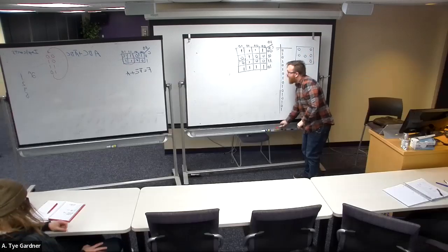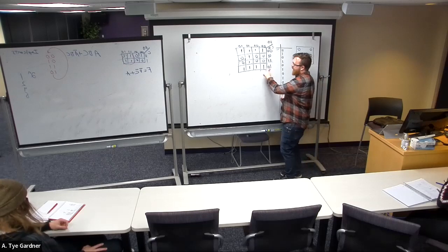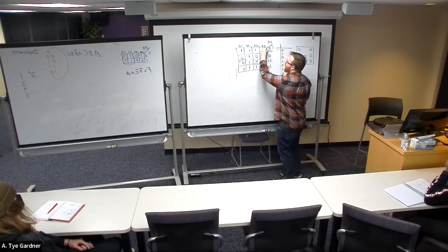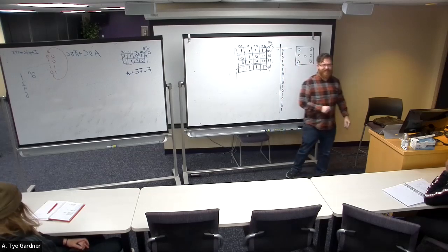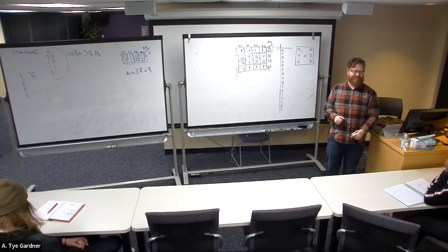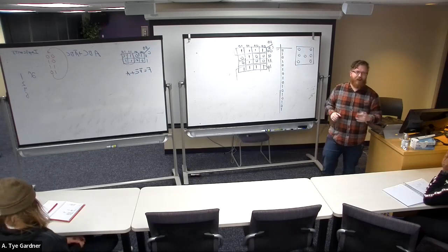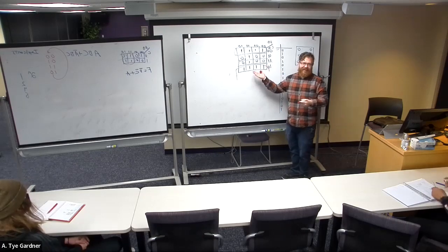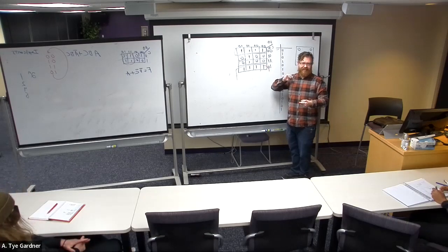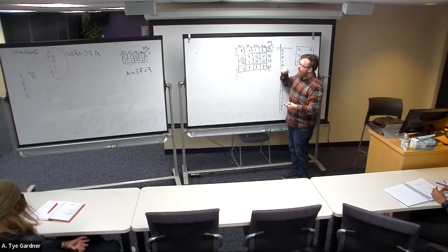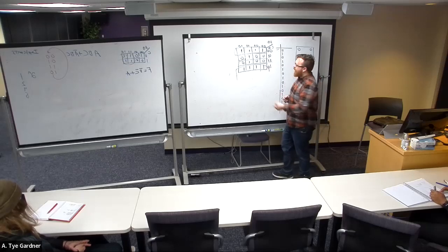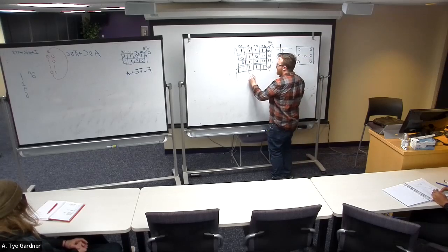So, this is the trick. See this? Those 4 ones are adjacent, but this is a rectangle. I told you, it's a trick question. Don't feel bad, right? I haven't shown you something that complicated. It's just fun. That is an 8 minterm implicant. That was a lot of simplification that you would have to write and go through with Boolean algebra. I think the rest of you probably got this one.